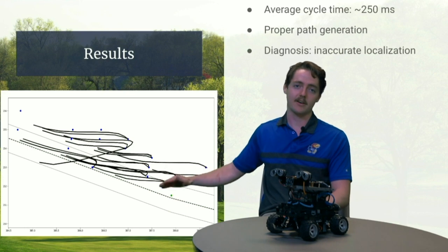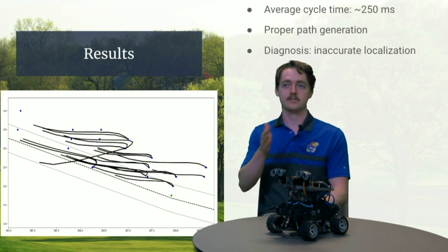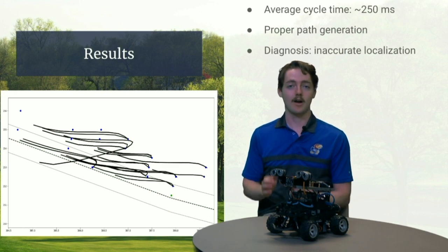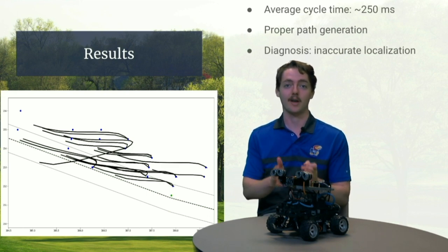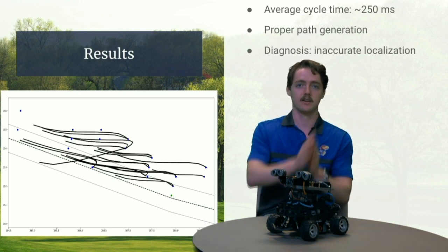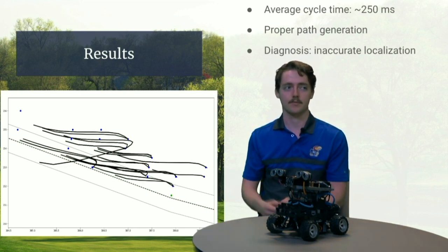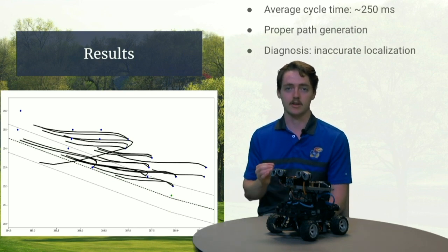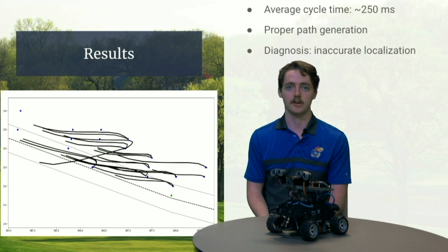It was trying to get back onto the cart path, and the controller successfully carried out those commands to get it back onto the cart path. However, because CADD-E was actually on the cart path the whole time, it really just ended up swerving off to the side, which caused it to run off the path. So the issue here is pretty simple. The localization is not accurate enough for our needs.